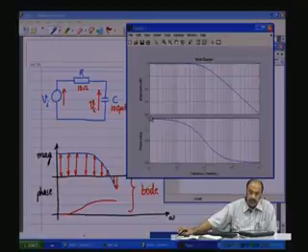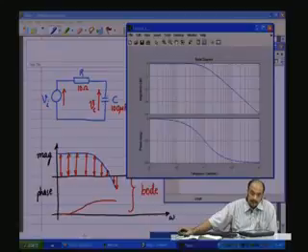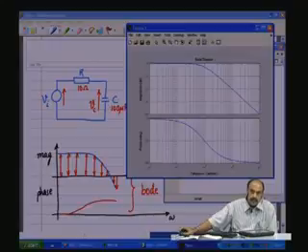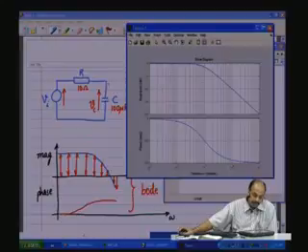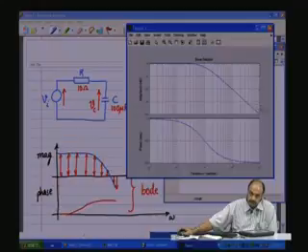When the frequency is 0, it is DC, and when the frequency keeps increasing, it becomes higher and higher frequency. During the frequencies which are DC and close to the DC, this capacitance is something like an open circuit. Whatever you apply at the input comes to the output. And during the portion when the frequency starts increasing still much higher, the capacitance starts giving lower and lower impedance. Ultimately, at very high frequencies, this will act as a short, and the output will go towards 0, and therefore, the attenuation keeps going.